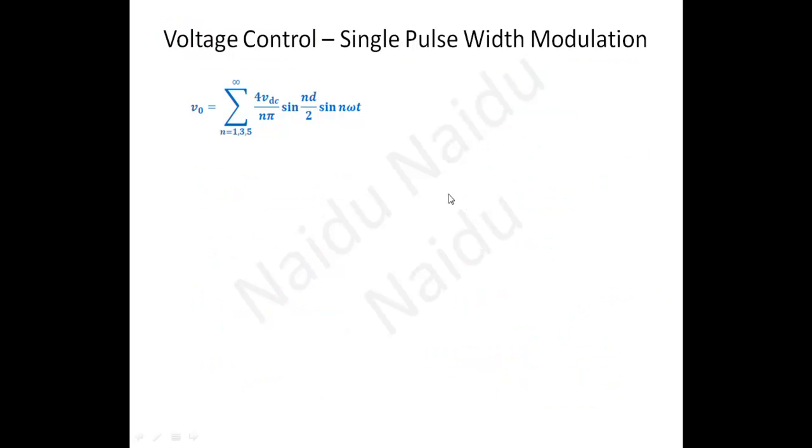Moving on. We already discussed that by setting the pulse width, we can eliminate a harmonic. Instead of pulse width, we can also represent the same thing with the help of alpha, but it will give you only one value. To set alpha to eliminate the nth harmonic, we take 90 divided by n, where n is the harmonic number to be eliminated. If you want to eliminate the third harmonic, n equal to 3, then alpha to be set is 30 degrees.